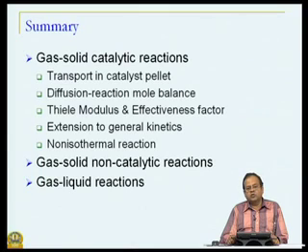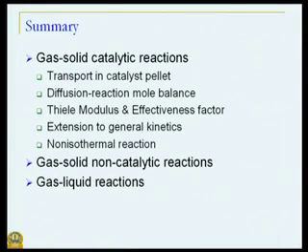What happens because of this time dependent characteristic? We actually now have to define how we calculate the conversion, or what is the time for the entire catalyst or entire reaction to be over. One way of doing this is to find out, for example, if you are looking at a case where solid is disappearing, what is the time required for complete disappearance of the solid, such as burning of carbon, for example, in which case our 100% conversion refers to the radius of the carbon